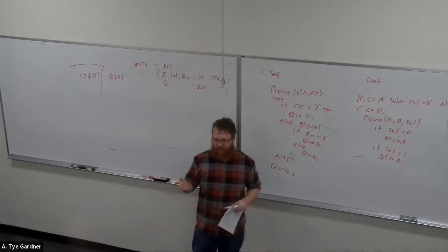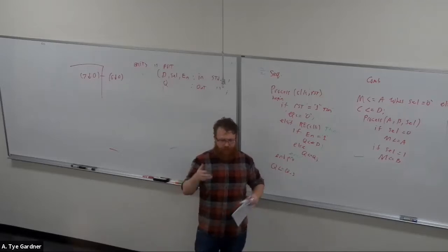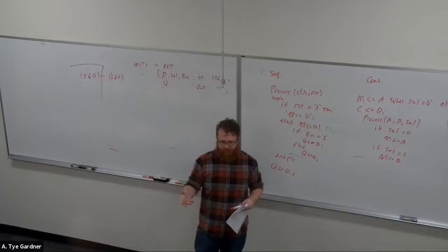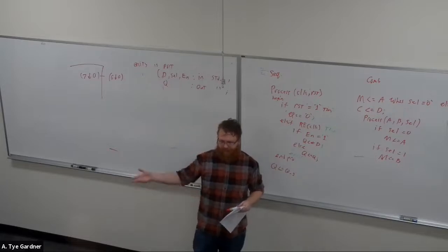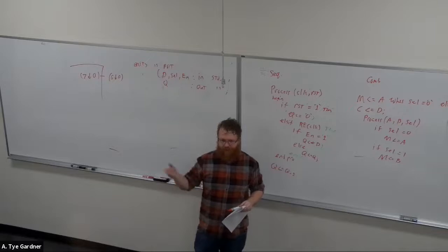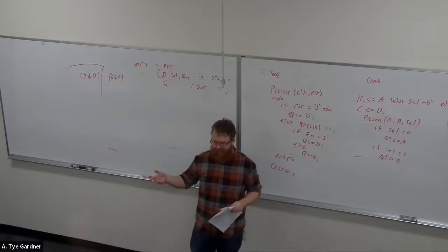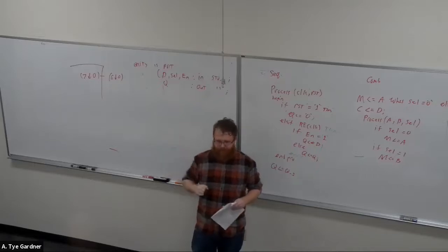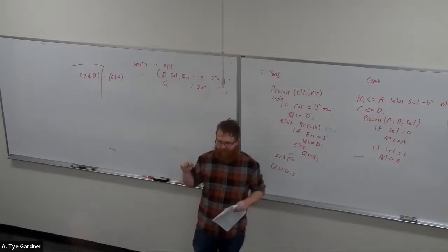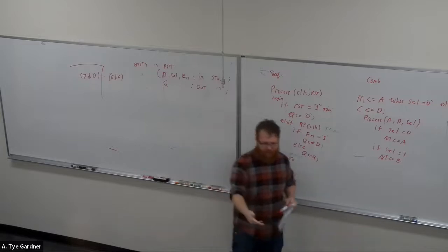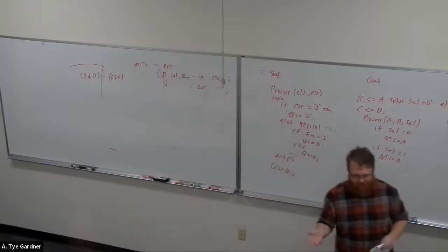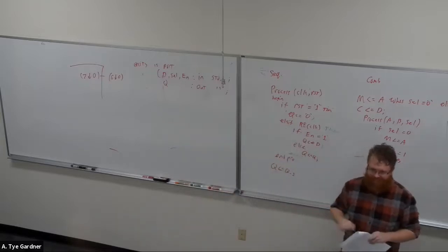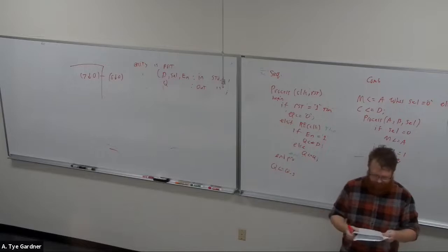So, for example, the dumbest way that I could do it is I could give you a full adder component and say, write a top level module for me that uses this full adder to make a 2-bit adder, right? And then you would write two component instantiations, you create an intermediate signal, ta-da, that takes the carry out to the carry in. So I'm asking you to implement components that maybe you don't even know what's inside of them, but you should know how to connect things together to achieve the goal.